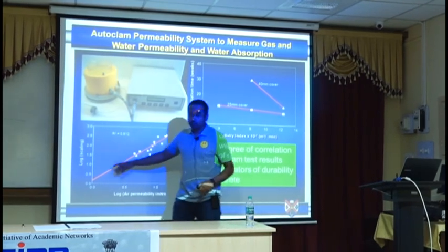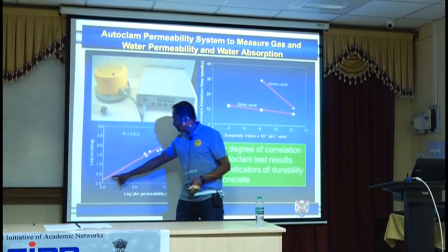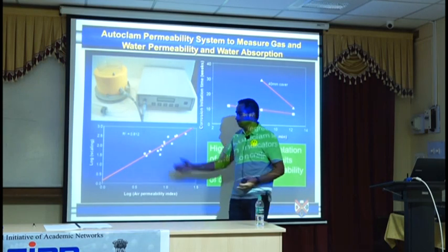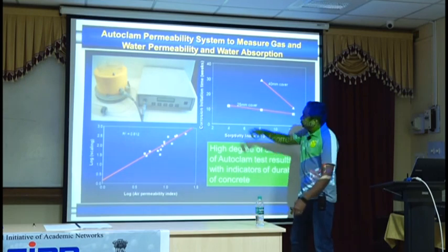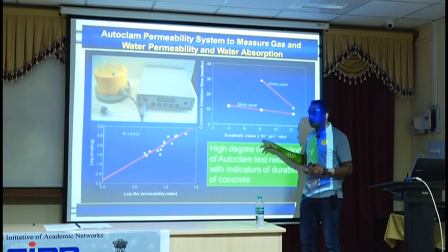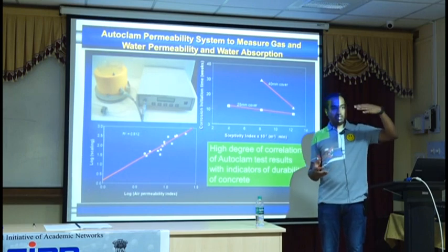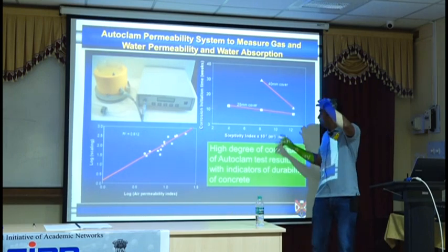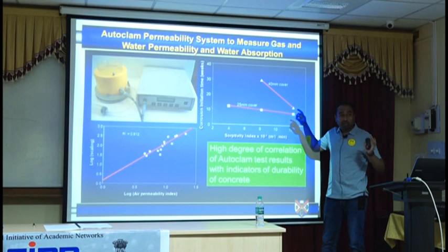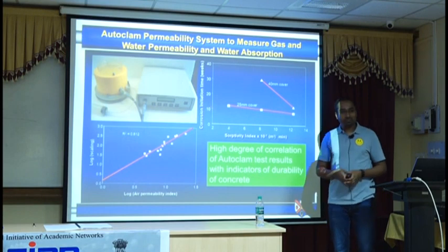And so this is for freeze thaw scaling. Due to freeze thaw, scaling is the falling apart of the particles. And as the permeability increases, you would expect the scaling to increase. That's what you're seeing by the linear curve. Corrosion initiation time in weeks will drop as the sorptivity index increases. Sorptivity index increasing means it's a very connected pore system. So you should expect corrosion initiation to happen much faster. These are bad concretes, these are good concretes. Cover has a large role to play, so don't expect every cover to have the same relationship. Don't expect every concrete to have the same relationship.